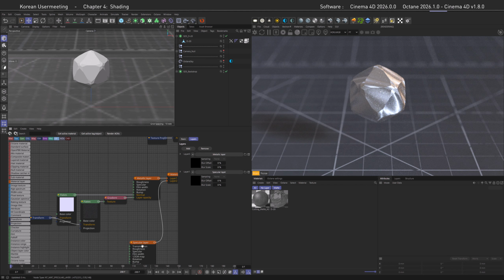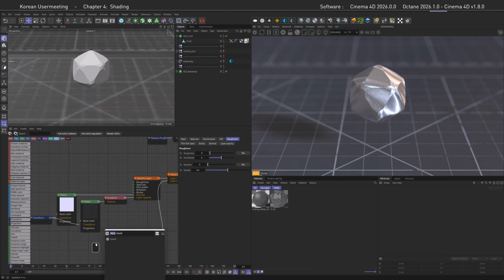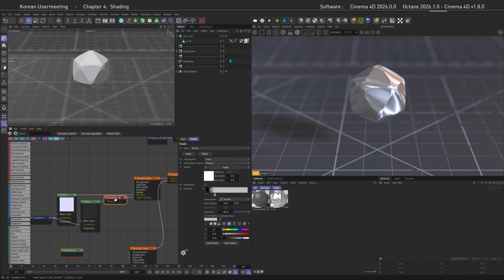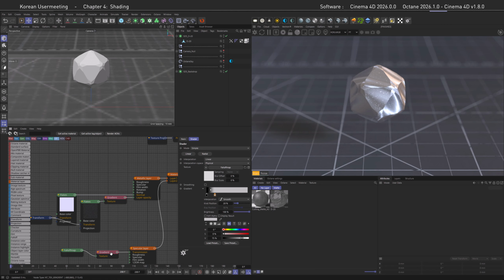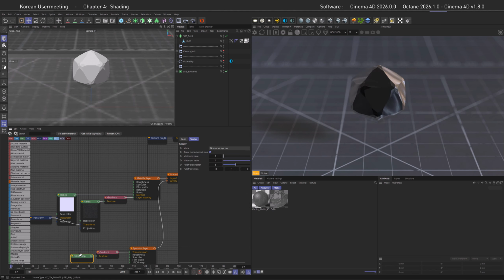let's create a specular layer as sort of a coating around the object. If you watched my recent Opal tutorial, then you know what's coming. We will create a fall-off map, then steal the gradient here from above, pipe the fall-off through the gradient to the transmission slot of the material, and then solo the fall-off.